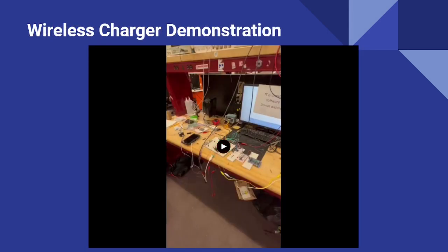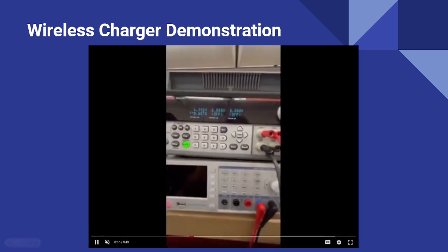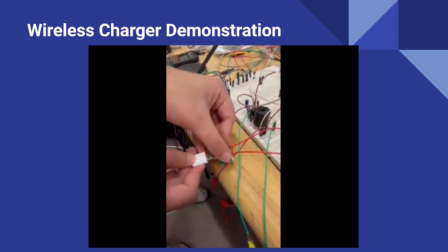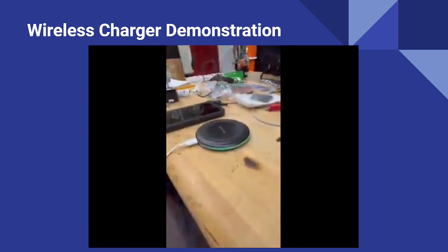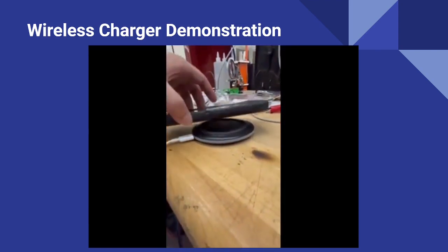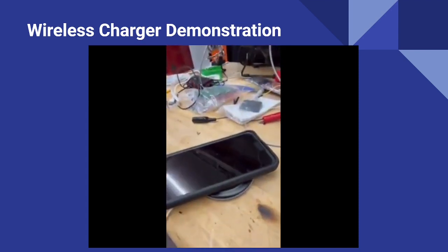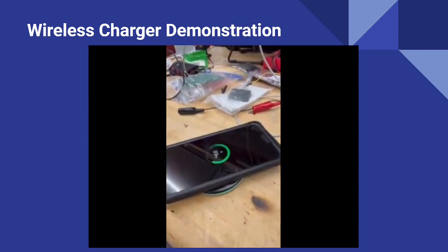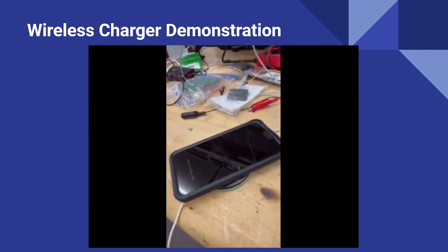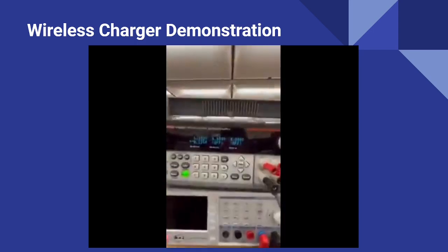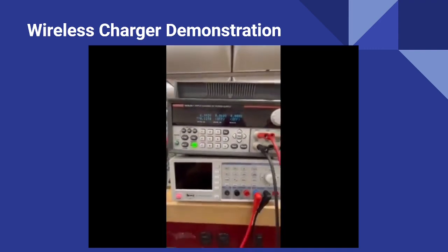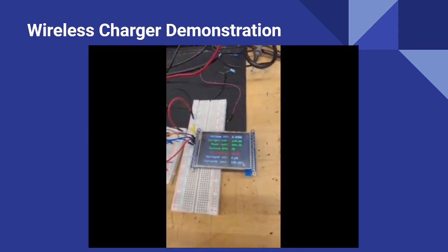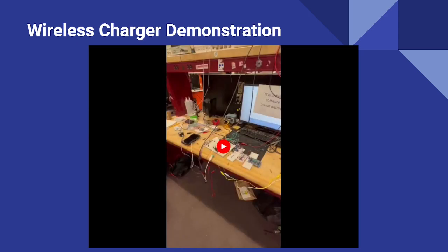And here we have the demonstration for our circuit powering a wireless charger, but unfortunately, when attempting hand cranking to power the charger, it was not working very well, so we decided to replace the motor with a 7-volt 0.5 amp constant source to show the minimum power values we need to power this device. However, we expect with a constant or a better, more constant RPM, we'll be able to power it in the final.